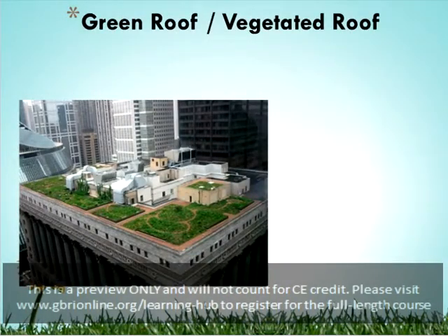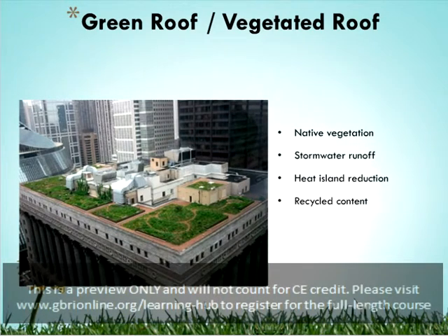Green roofs are sometimes referred to as vegetative roofs, garden roofs, or living roofs. A green roof is a roof that is partially or completely covered with vegetation. Usually the vegetation is planted in containers, modular units, or bags that sit atop a waterproof subsurface. Rather than soil, an artificial growth medium is typically used that is lighter and provides more nutrition for the plants.